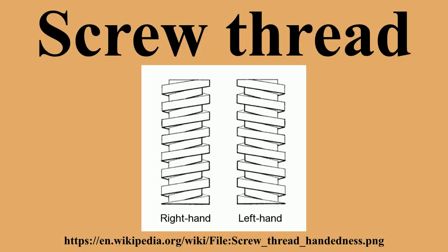However, this ideal condition would in practice only be approximated and would generally require wrench-assisted assembly, possibly causing the galling of the threads. For this reason, some allowance, or minimum difference, between the PDs of the internal and external threads has to generally be provided for, to eliminate the possibility of deviations from the ideal thread form causing interference and to expedite hand assembly up to the length of engagement.